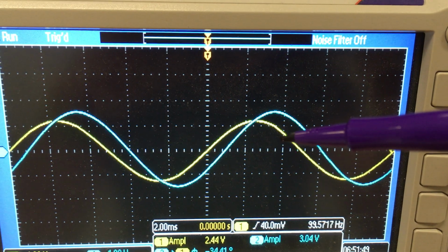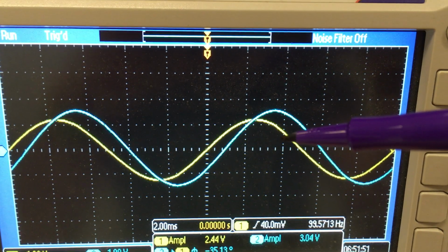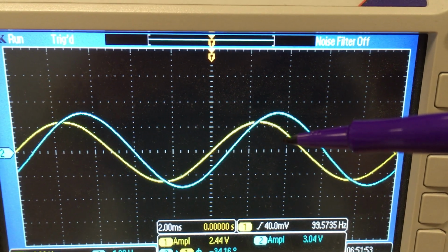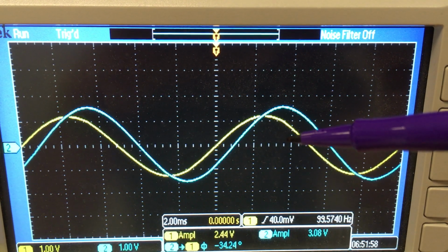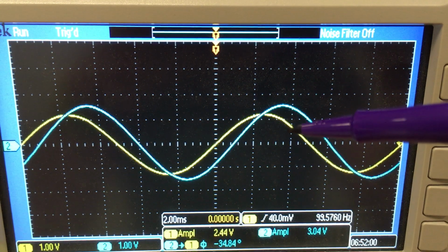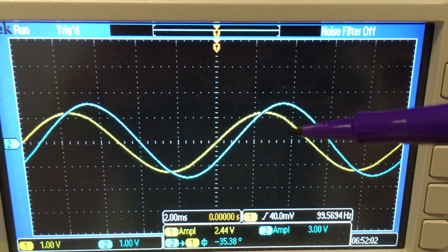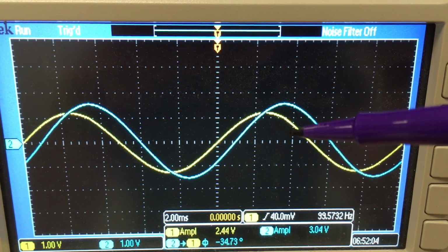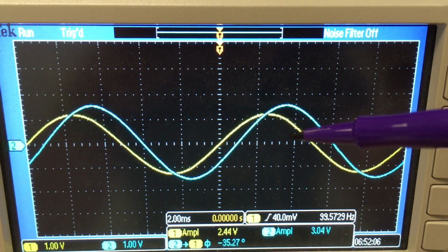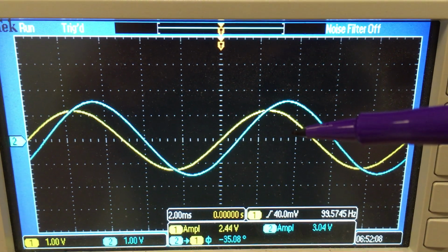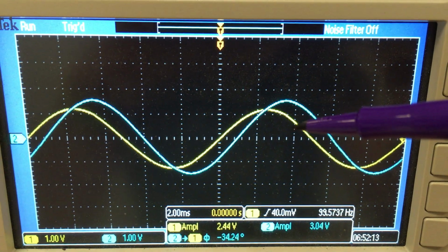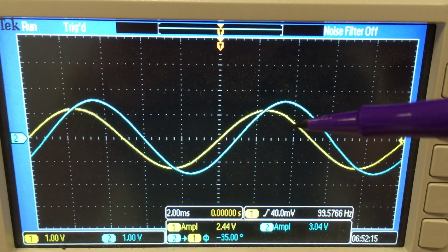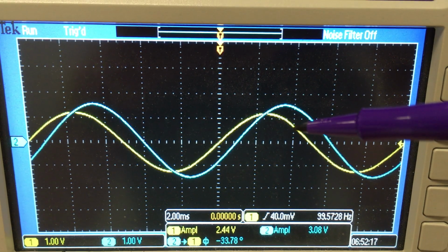As you put more and more charge onto a capacitor, it gets harder and harder to push more charge on there, because you're having to put another negative charge closer and closer to a bunch of other negative charges. If you have a ton of negative charges on there already, it becomes a lot harder to push that next negative charge on, because of the Coulomb forces that we talked about right at the beginning of the course, because of the huge Coulomb forces between those charges.